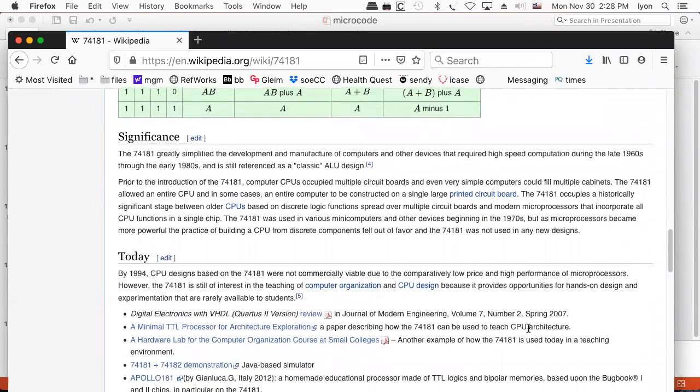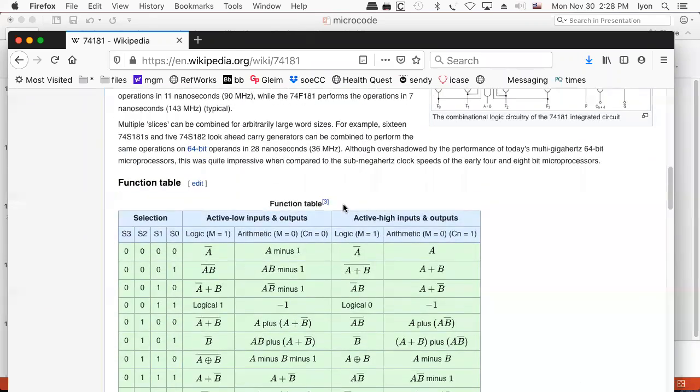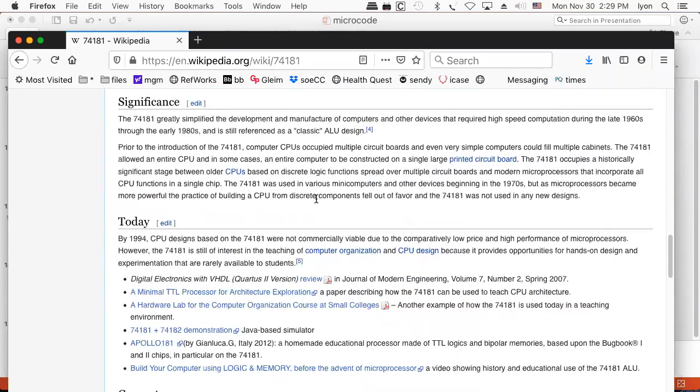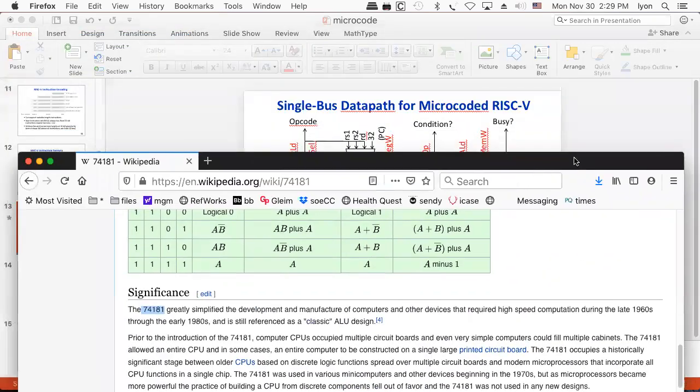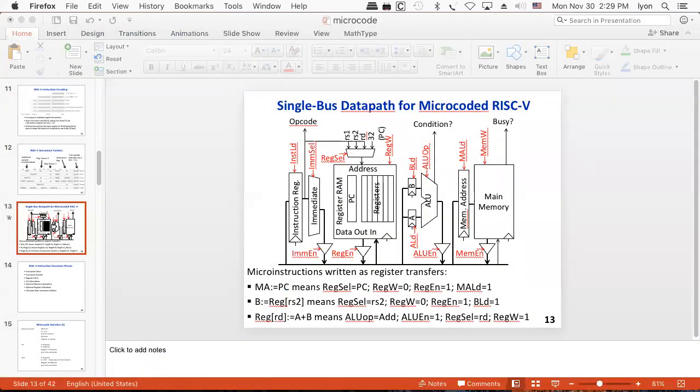But it's interesting to note that you could build your own computer using this discrete logic and then proceed to do your own microcode. And in fact, if you look at the original PDP-8s, you couldn't open up the box and find the CPU because it was a bunch of these chips, these 7400 chips that were used to create the CPU. And so you couldn't find the microprocessor because it was distributed across many TTL chips. So that's an interesting point. All this stuff got started from the old days of TTL.